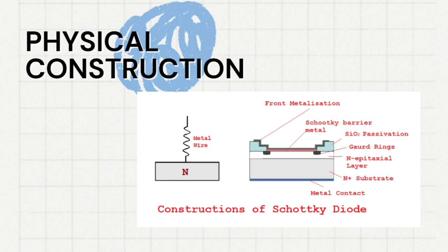When a Schottky diode is forward biased, the current flows because of the majority charge carriers, that is, electrons. When a Schottky diode is reverse biased, minority charge carriers are absent. So, reverse saturation current conduction stops instantly.